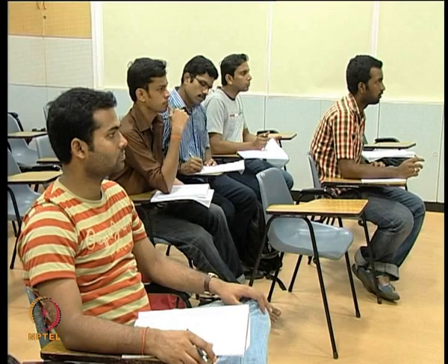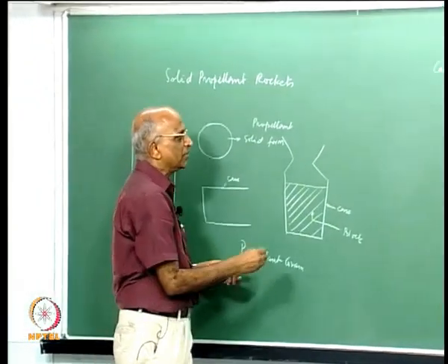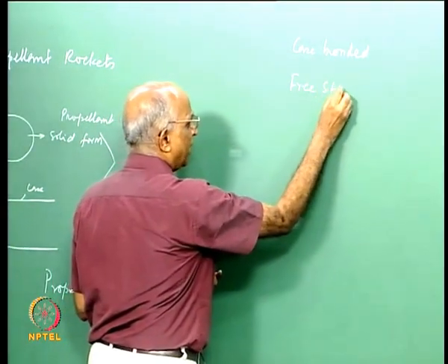It is also possible to make the propellant in the form of a paste and extrude it out, just like we squish out toothpaste from its container. We could thereafter cure this squished out paste in a furnace and enclose it within a sheath, and then I charge it into the case, in which case it is known as freestanding.